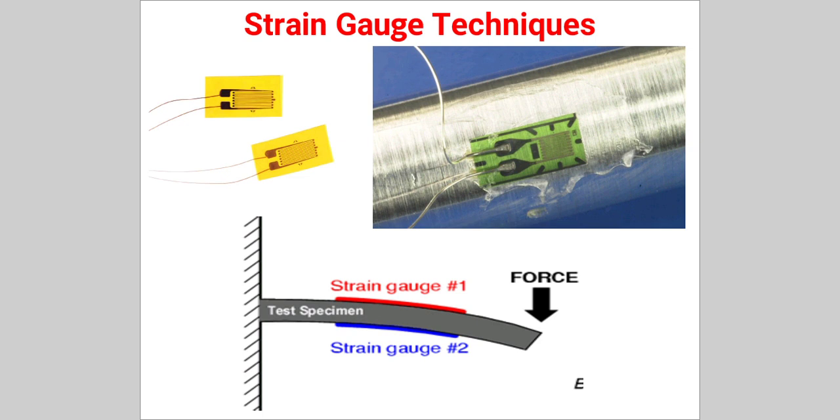If the metallic strain gauge comes in contact with water, its resistance will change, and corrosion of that particular strain gauge also takes place. Therefore care should be taken. Metallic strain gauges should not be in contact with temperature and water. But if we have to use strain gauges in water applications, at that time we have to use the non-metallic, or semiconductor type of strain gauges,